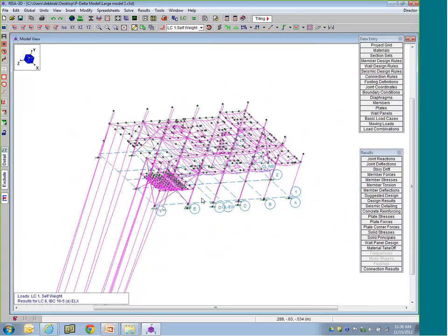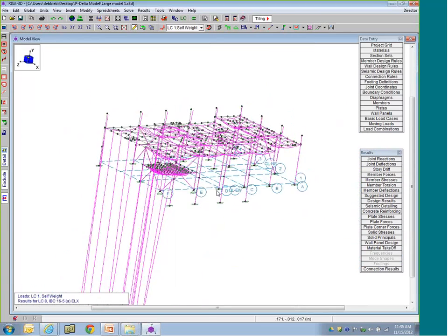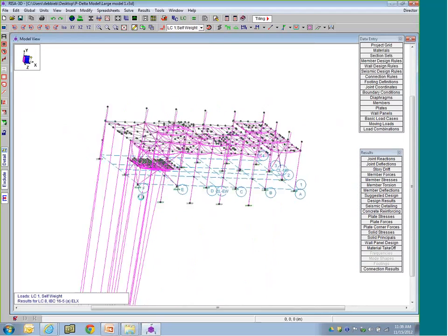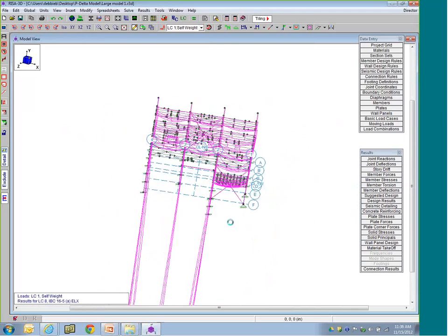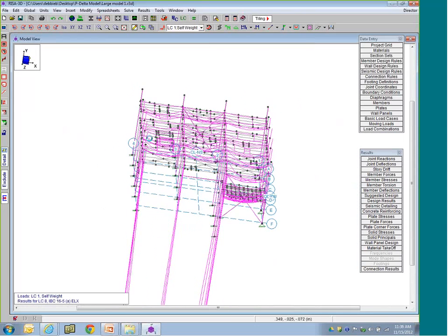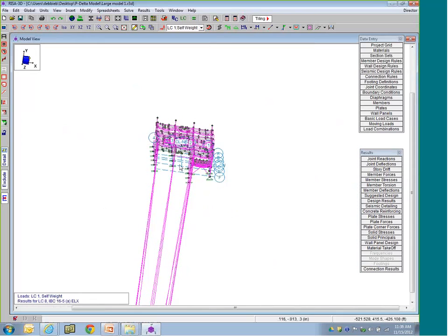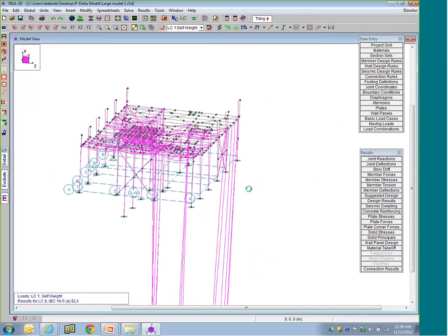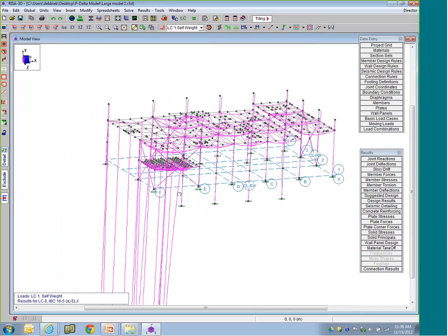So this is going to tell me a lot more of the story. It appears that the entire section where those members are failing is going off my screen. I really can't even see where it goes. It just goes beyond the screen. This is a typical thing for P-Delta divergences, where you can't really even see what's going on because it's just blowing off the screen.